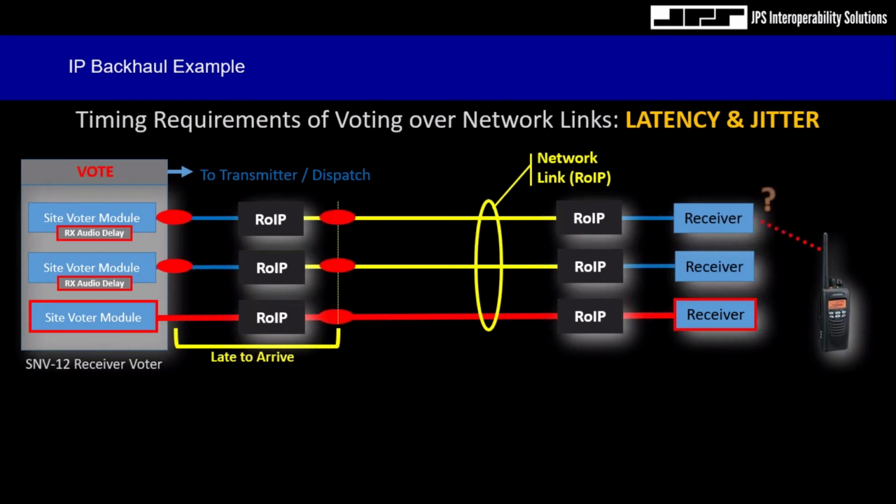exact same moment. But later in the day, I might receive a call from dispatch reporting a voting issue, and lo and behold, my previous receive audio delay adjustments are no longer valid, as the network latency has changed over time due to saturation. Again, this variation of network latency over time is what we call jitter.